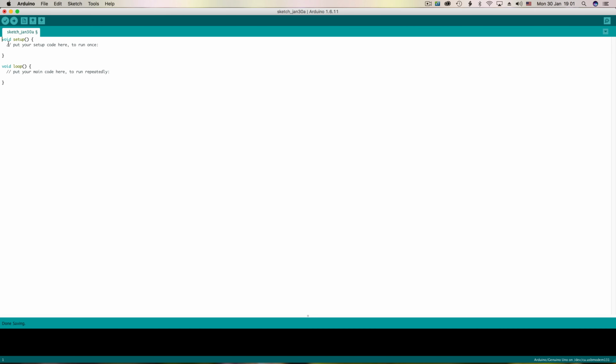So basically 0 will represent 0 volts and 1023 will represent 5 volts on the pin. So the 5 volts will be split into 1023 equal parts, allowing you to read very precisely, therefore getting very accurate measurements. For example, if you're reading the values of a temperature sensor, you will be able to calculate the temperature precisely, therefore your system will have a smaller margin of error.